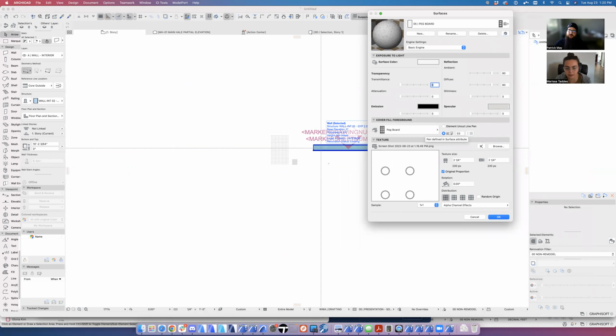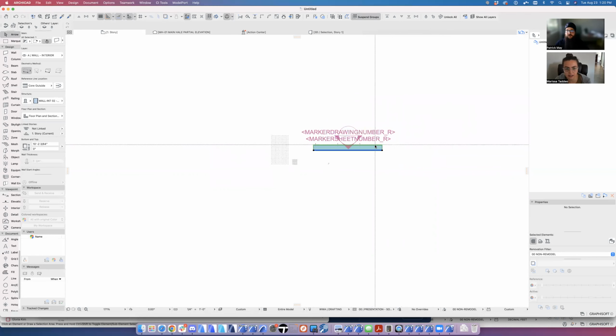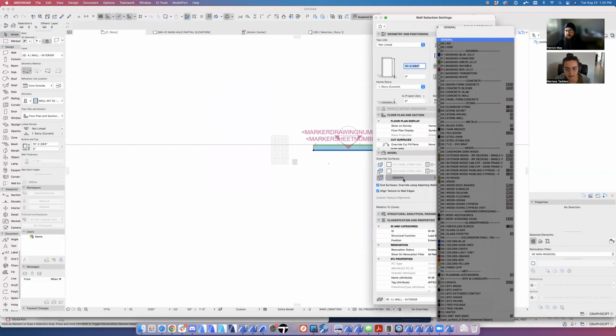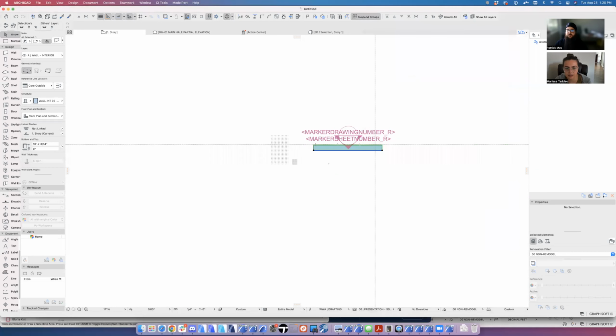Oh, okay, great. So if I want to change that surface, if they're like, oh, we're not going to have the pegboard on that, then you just come back in here and say this is going to be gypboard or some other surface. And you're not going back through and tracking down where the fills were and how many you had on each wall. It's just part of the model at that point. Perfect. Okay.